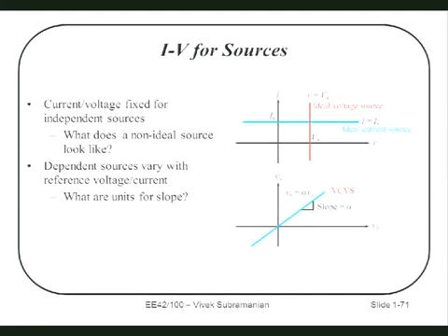For a current versus voltage characteristic, what does the slope indicate? And I'm going to ask you here. If I take this slope, and remember, the slope of that is dV/dI. What are the units of that slope? So remember, V is equal to IR, so R is equal to V over I. Good. That's units of resistance.